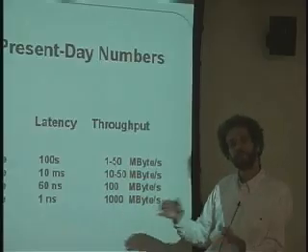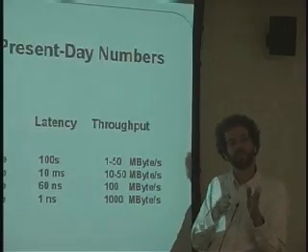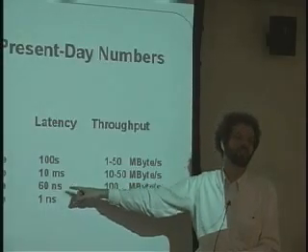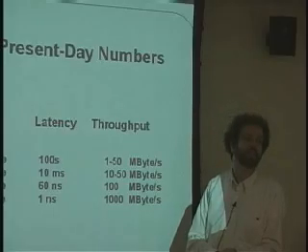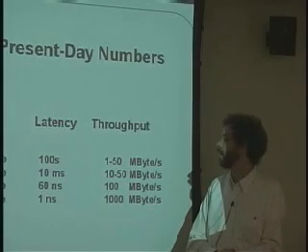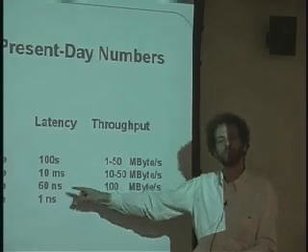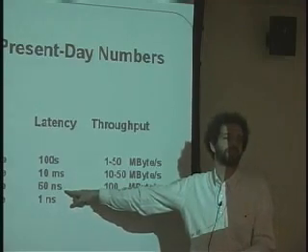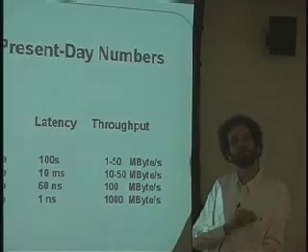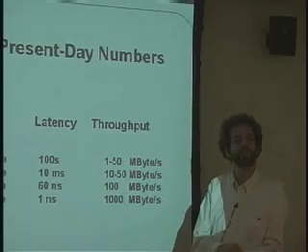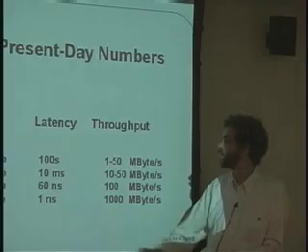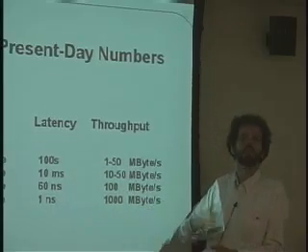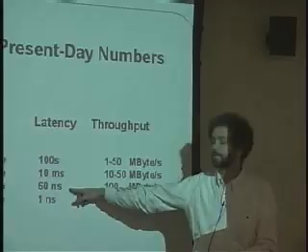That's true, but keep in mind that the DRAM itself is heavily pipelined. It still has a latency of 60 nanoseconds to get the first word. They don't talk about that when you buy it, but it's true. What that means is that if this were used to implement the register file, we'd be in trouble, because our machine is running maybe 60 times faster than this. Every time it wants a new location in the DRAM, some random new spot it hasn't accessed before, it has to wait 60 clock cycles to get it. Never mind that it clocks out much faster than that once it begins to go. The latency is very long.